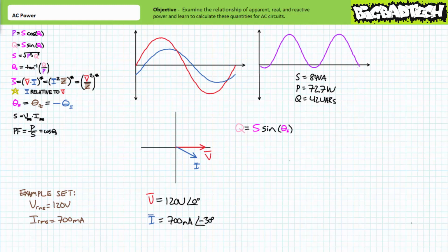Reactive power equals apparent power magnitude times the sine of the apparent power angle. From our previous calculation, we have the magnitude of apparent power, but using the old school methods, we're not directly aware of the angle. This being said, given we know power factor to be 0.8660, after all, it says it right on the side of the box, we should be able to determine this angle.